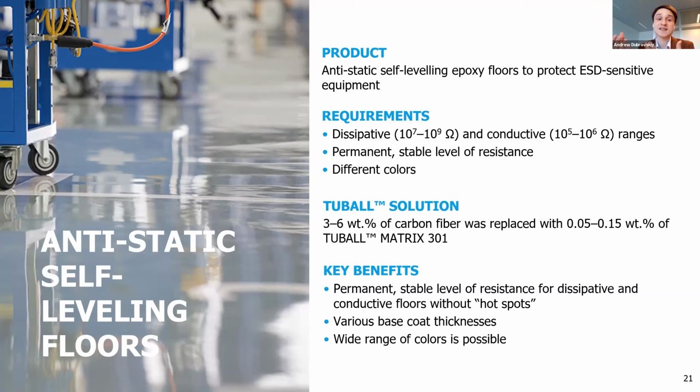And we fully understand that if they were using chopped carbon fiber, in this specific case, they would have never achieved surface to surface conductivity, because all systems filled with chopped carbon fibers are working only if there is a highly conductive primer. And in our case, our single wall carbon nanotubes provide the ability to perform very good surface to surface conductivity and surface to ground conductivity even without primers.